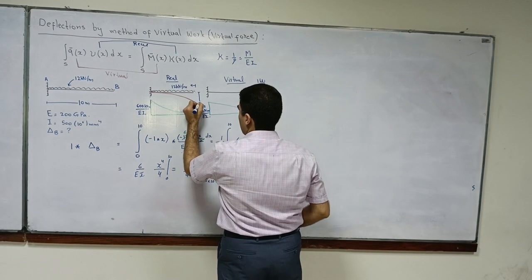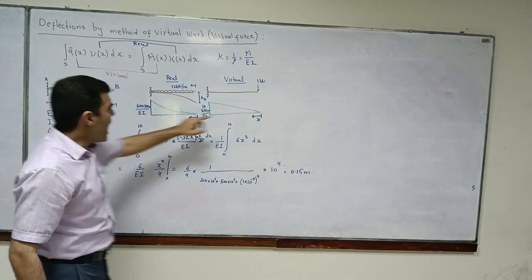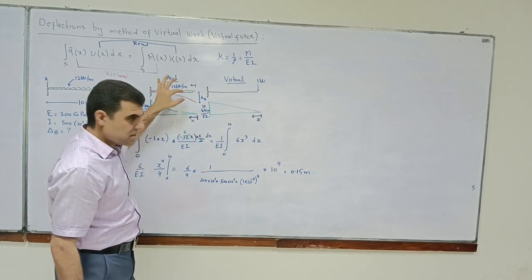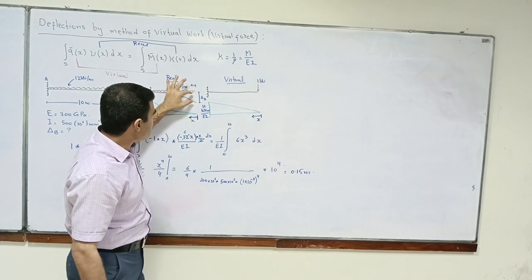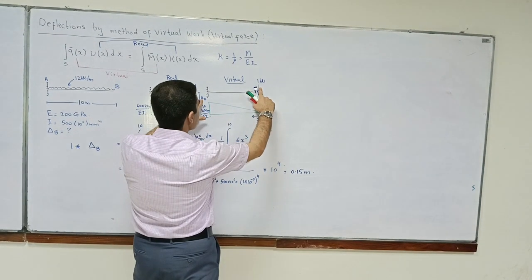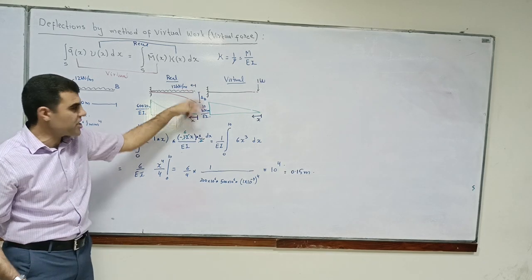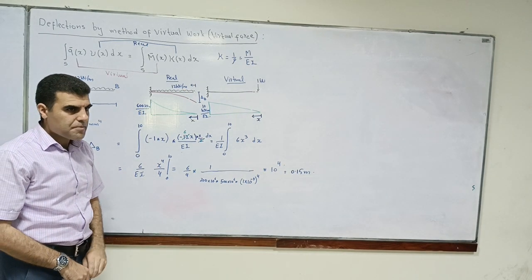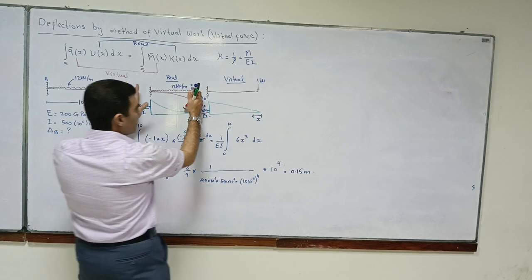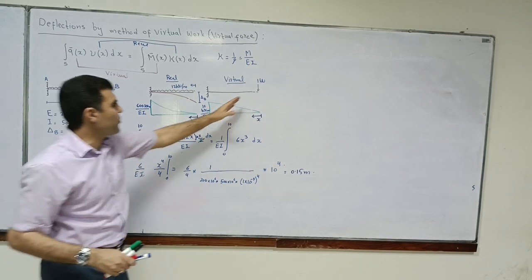Sir, we don't have to deal with that integration. So in the integration, you have 1 times this one. What is integration? You have got load times this displacement profile. This displacement profile is continuous, but you have got just one load and 0, 0. So you multiply each of them, 1 times this, and over here it's 0. So 0 times this, 0 times, so everything becomes 0. So you add it up, you get just 1 times delta V. You understand? So it's only in this integration, which is along the whole length, it's only this times this which is active. Okay, the rest is all 0.